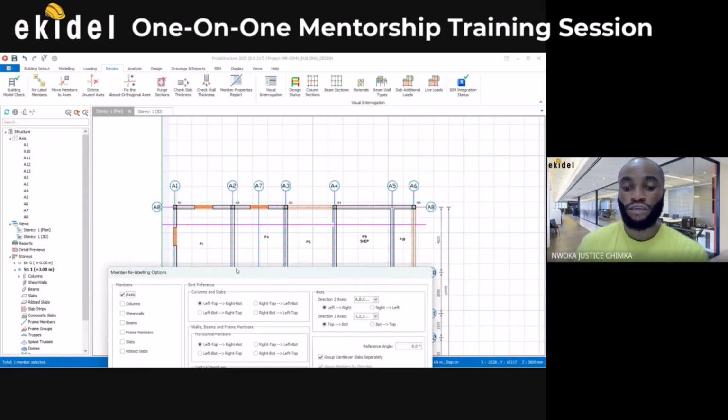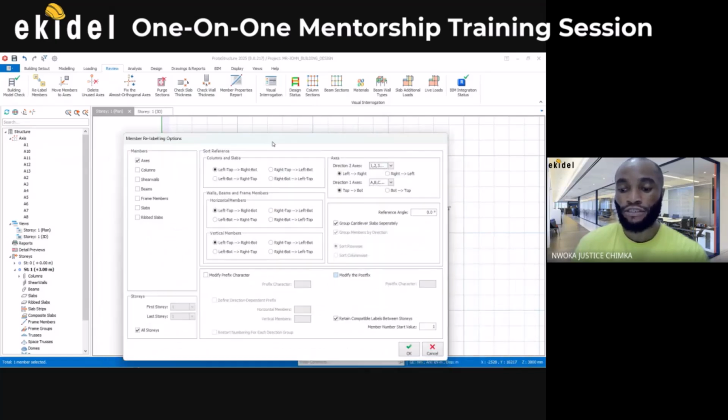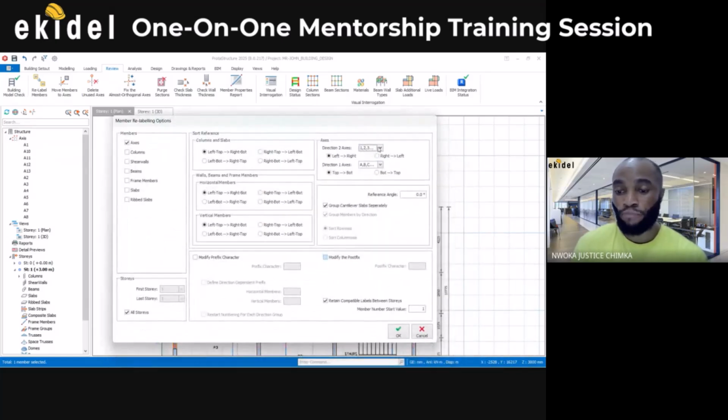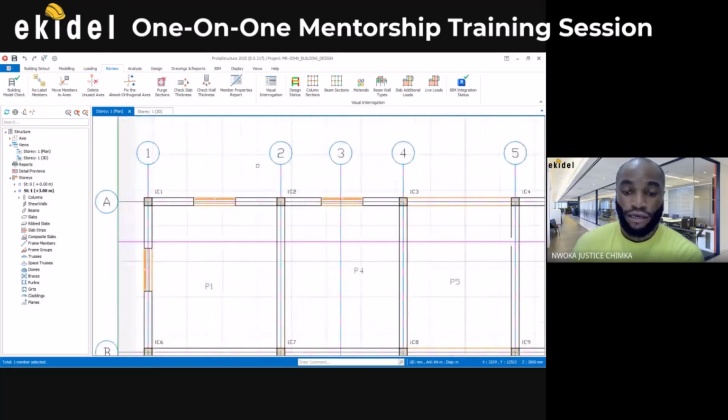Direction 2 is the vertical axis. So now I want the vertical axis to be 1 to 3 and not ABCD. And direction 2, which is the one going horizontal, as ABCD. So once I've picked this, I'll then say okay. You can see that they have all changed now. Can you see that?